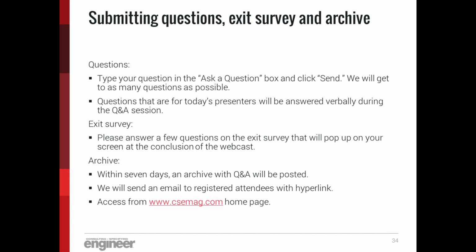You know, imagine shutting down the generator on an entire hospital campus while that's the only power source and the hospital goes completely dark. So we want to know. It's a good question because we want to know if we have a ground fault, but we want to alarm in that condition. We don't want to trip the entire system in that condition. Any individual ground fault requirements are also listed in NEC, and those would be at the branch circuit level, but not shutting off the entire facility.